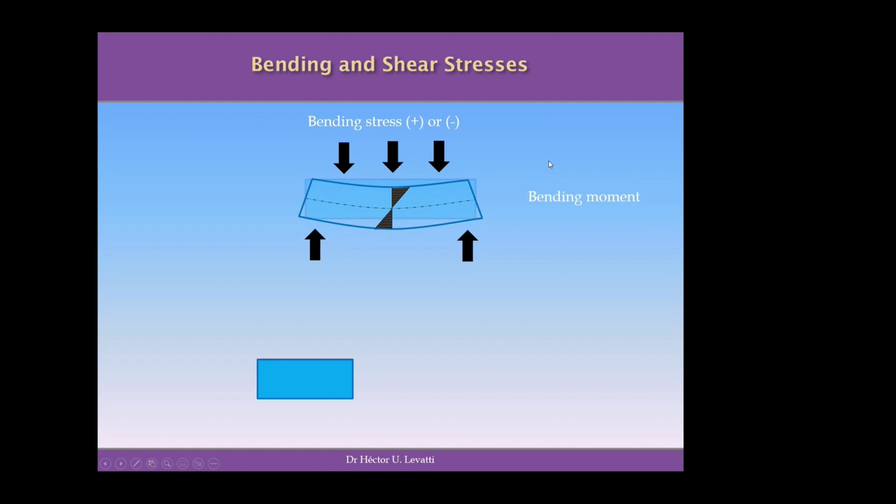So this is what we call, if you remember, we have defined the bending moment. So these are the moments you can calculate internally in a beam. And these bending moments are the moments that produce these bending stresses. And in here, you can see as well a few of the cross sections you can have in a beam, and you see clearly that in this case, this cross section at the extreme is the one that rotated the most. And the one in the middle is the one that didn't rotate because in this case, the loads and the beam are both symmetric.